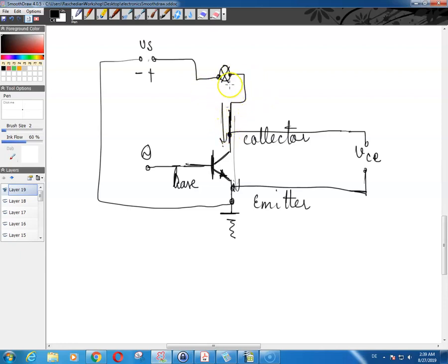So in short, you have two different concepts related together when it comes to power. There is the power which is dissipated on, let's say, the emitter junction of a transistor or on a resistor or something like that. And then there is the power dissipation rating of that electronic component. Both of those things have to match in order for the circuit to be running properly. That's important.